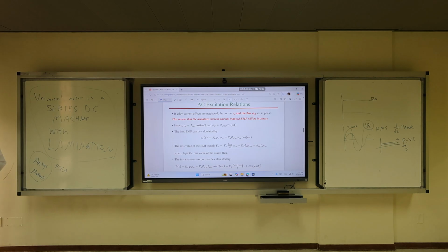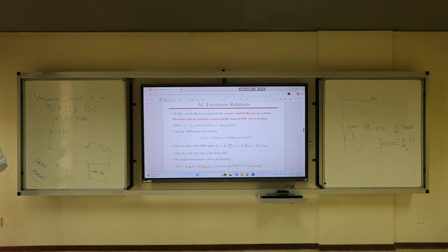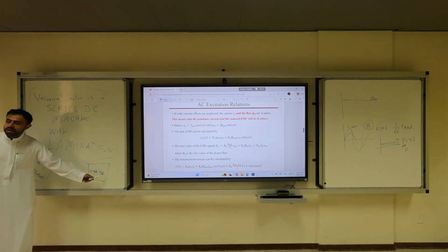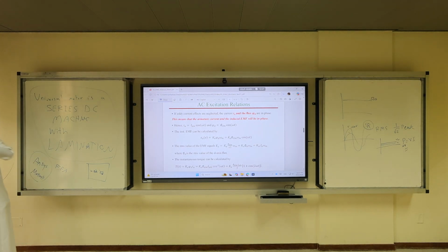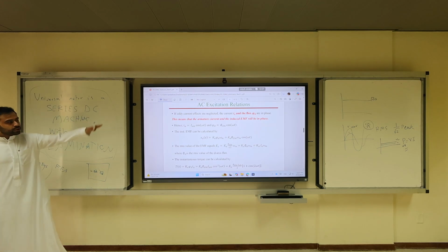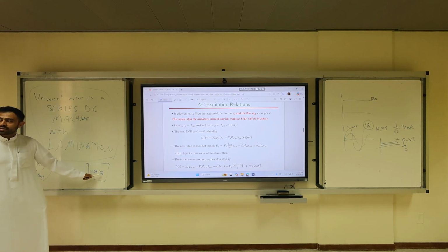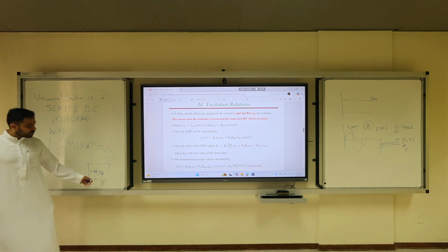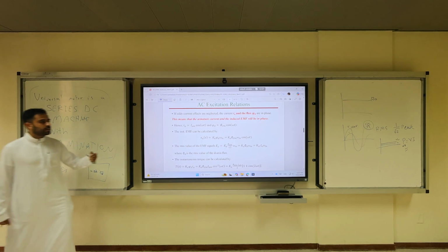You would notice that always in the model, you have to check a box called include eddy current. If you include eddy current in your calculation, it will add another equation that's a function of frequency squared or frequency to the power 1.5. So if you do the analysis using the equation and you go to the software, you have to uncheck it. This is just for your mind. Would it matter? Yes, a little bit, maybe 5, 10 watts in your calculation.